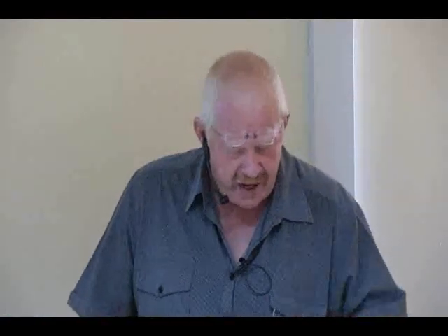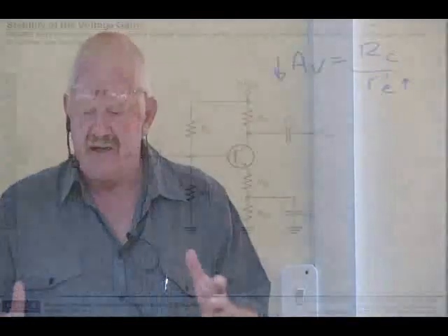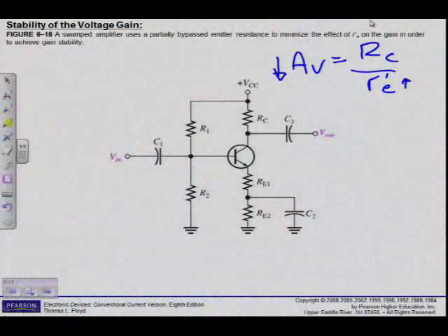Alright, so with no bypass capacitor, the gain is decreased because RE is now in circuit. So, how do I get rid of this problem? R'E changes with temperature and IE. Although I get maximum gain, it's of no use to me. But if I include RE, what have we seen happen to the voltage gain? Becomes 1,7 something. Down from 152 in this example. Okay? That's also not a very good situation.